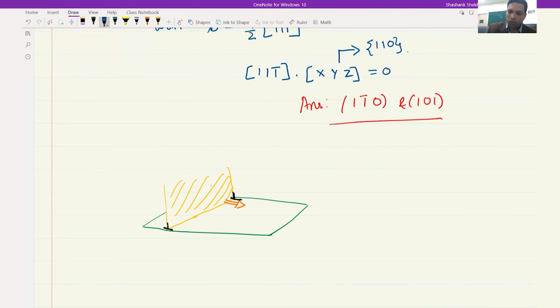But what happens if there is some, let's say, precipitate lying over here, and it is a precipitate which cannot be cut or sheared through, or made to disappear in any way? So this particular precipitate will remain here. What will happen? How will this extra half plane move? Okay, so with that thought in your mind, I will end this session, and we will continue our discussion about the motion of dislocations, for example, how to take care of this kind of problem. Thank you.